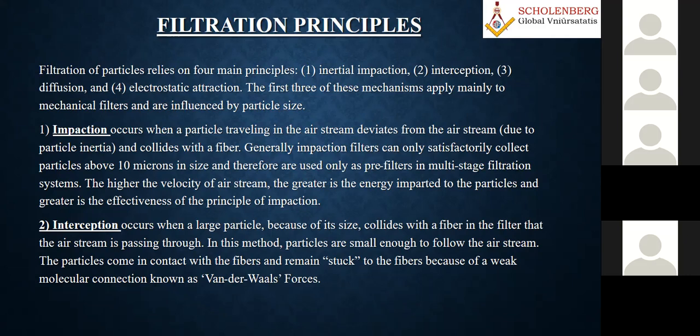Design is also like that. In filtration, the first mechanism is impact. As soon as the jet of air hits the filter media, it impacts, isn't it? The second is interception, and then diffusion. As I told you, you probably studied the diffusion principle in heat and mass transfer. The fourth is electrostatic attraction. The first three processes, impact, interception, and diffusion, apply mainly to mechanical filters. Electrostatic attraction is the last one, influenced by positive and negative charge.